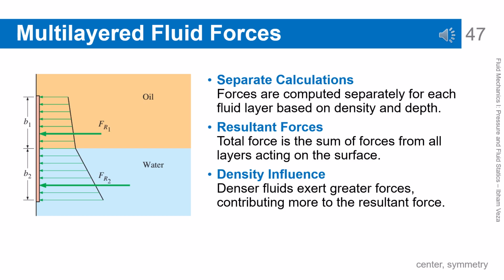Multi-layered fluid forces. If a surface is in contact with multiple fluid layers, the force must be calculated separately for each layer. Each layer contributes a force according to its density and depth. The total force is obtained by summing all these contributions. Denser fluids have a larger influence. This approach is important in stratified fluid systems.